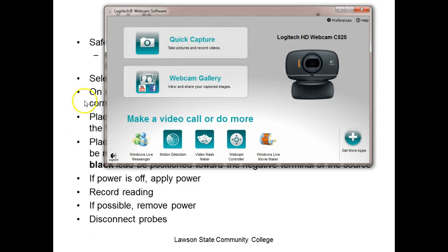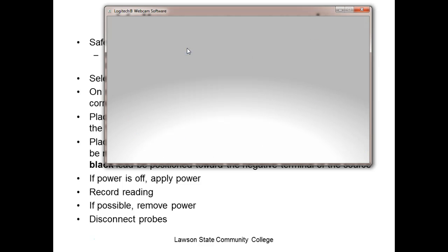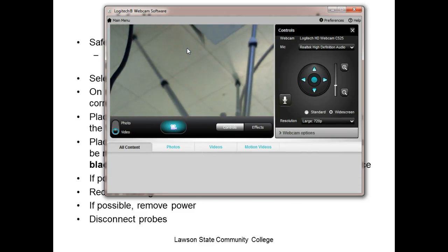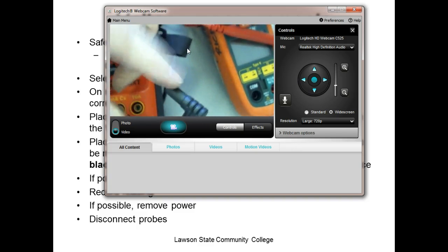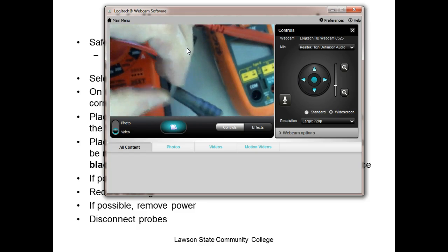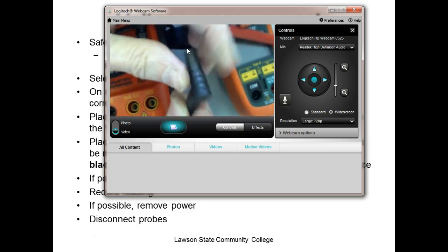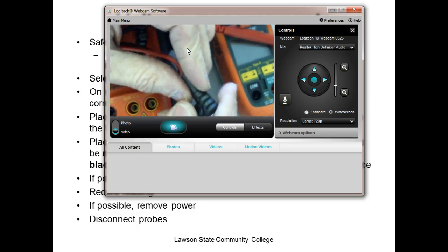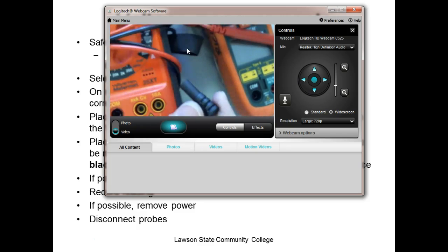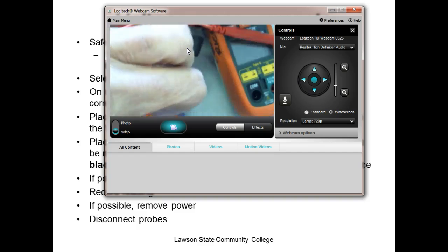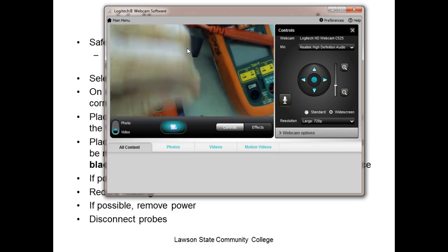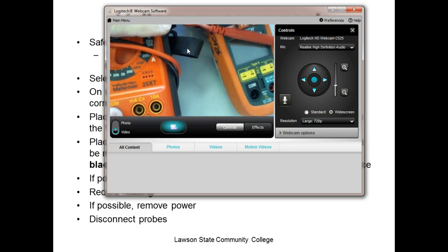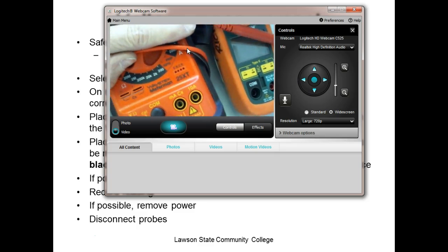So the leads that go into the meter, you see people cut these off because this is another one of those things where they cut them off to make it inconvenient. So what they do on your newer meters, as soon as I find my camera, is the actual leads that go into the meter, the banana plug is actually covered, because this happens all the time, where you actually didn't drop your meter, and you got alligator clips, and it falls out, and the leads pop out of your meter. Well, as soon as that happens, this right here is going to be electrically hot, right? You understand? So don't trim those off, but it makes it a little harder to get the leads in and out.